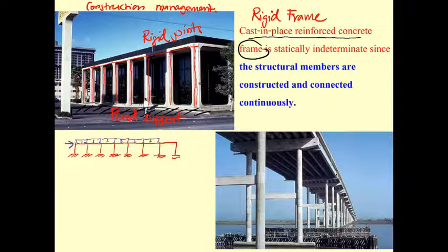And then the question is how do you draw the free body diagram of this. If you consider, since the supports are fixed, each of them is going to have 3 unknown forces: the vertical force, the horizontal force, and the moment. Each of the supports is going to have 3. So the total unknown reactions of this is going to be...